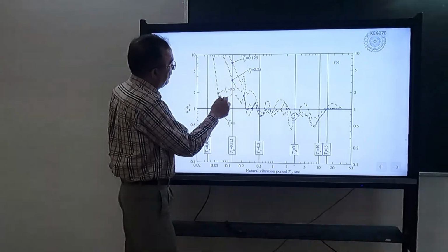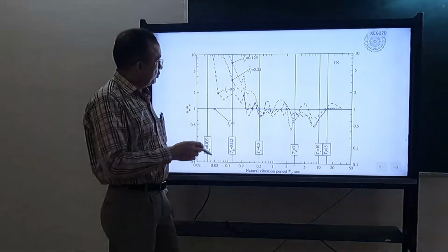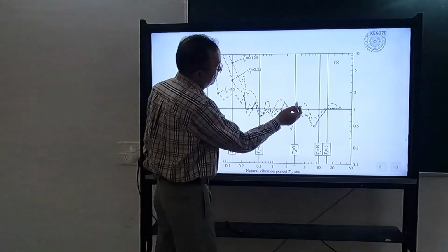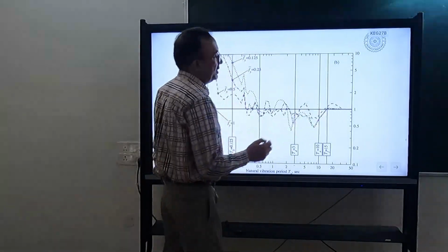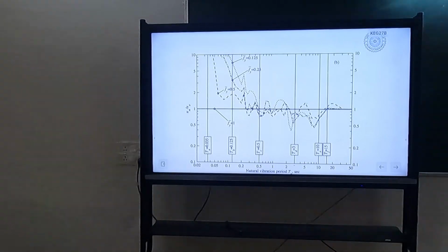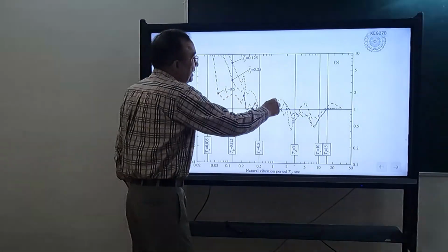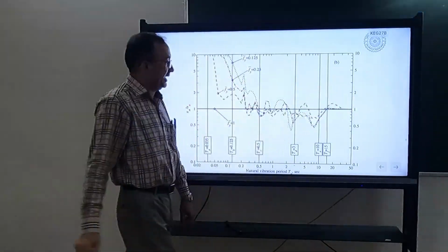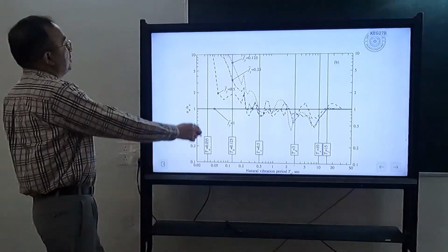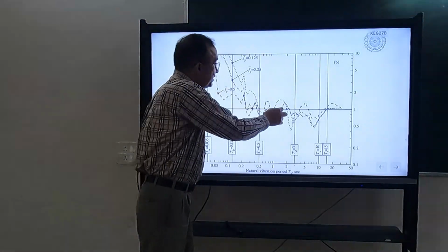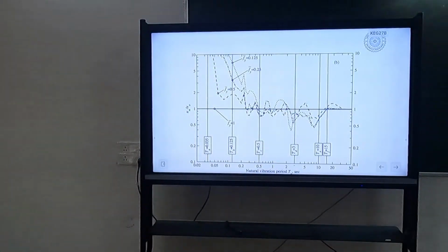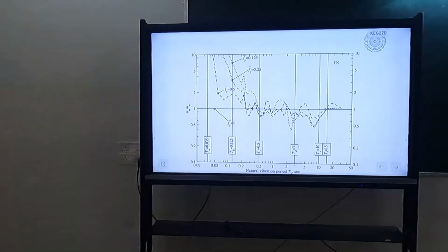These are for different values of Fy bar and for one earthquake. So you can see that beyond this T equal to 0.5 second, it is more or less 1. Okay, for one earthquake, it is zigzag because it is for one earthquake. If you will consider a number of earthquakes and then take average, you will get a smooth line corresponding to 1. What does that mean? That irrespective of the response reduction factor, the displacement is same in this period, means equal displacement principle.